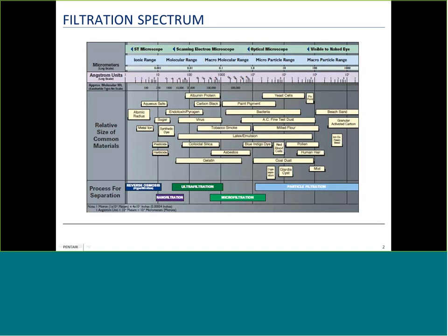Now, what is an ultrafilter? It's a mechanical separation process down as low as 0.025 micron, and it's a membrane-like technology, excellent for removal of suspended solids, high turbidity loads, and high silt density, and aluminum sulfate is a flocculant. And it's great for those highly turbid waters and surface water sources. I can think of the Mississippi River, the lower expanses of it.